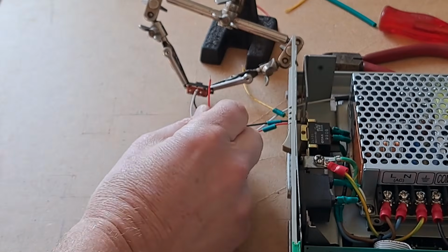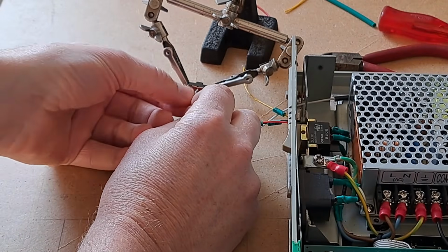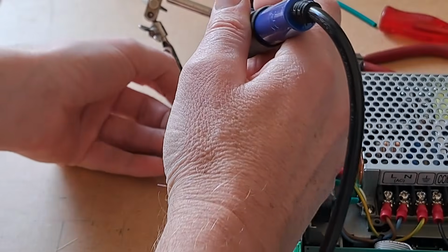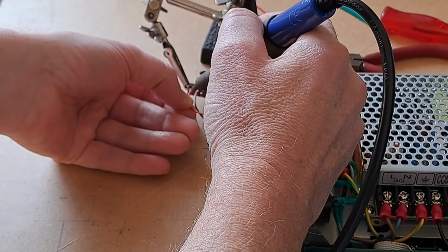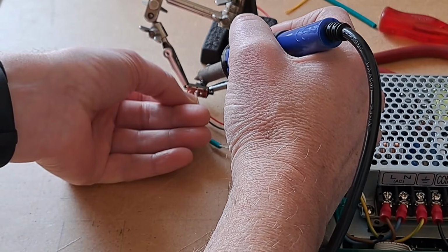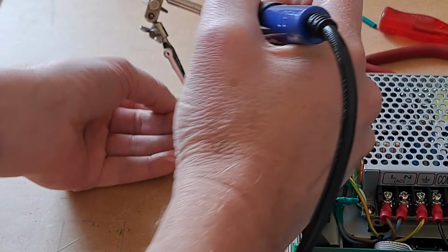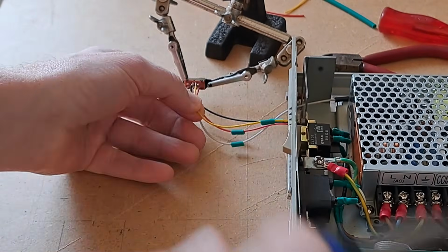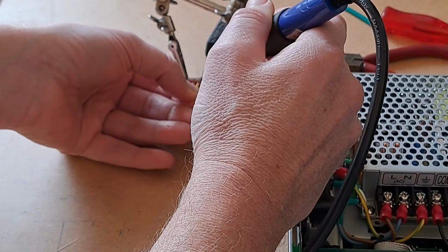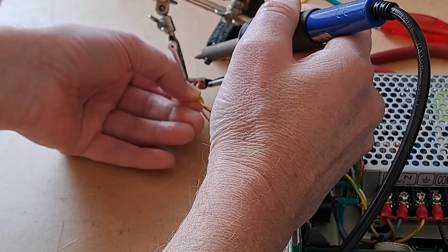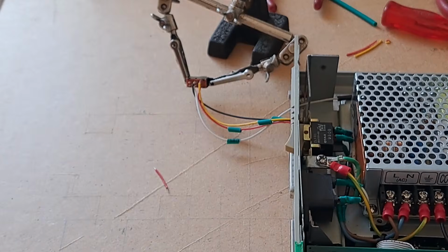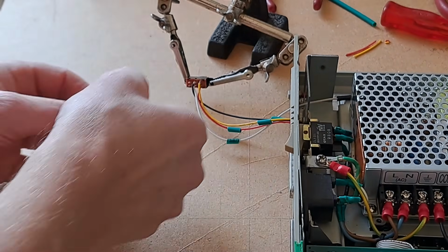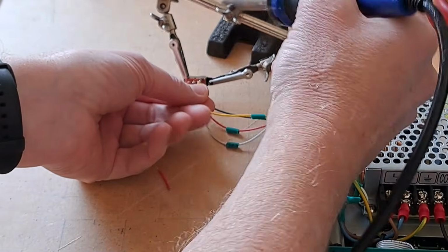And now the red wire. This comes from the drive 0 select. I connect it to the pin connected to the internal drive with the current switch position. And then we have the yellow wire from the drive 1 select. This goes on the same side, but next to the switch of the external drive. Then the drive 0 and 1 select also need to go to the other side of the switch, but crossed over. I will do that with these wires.